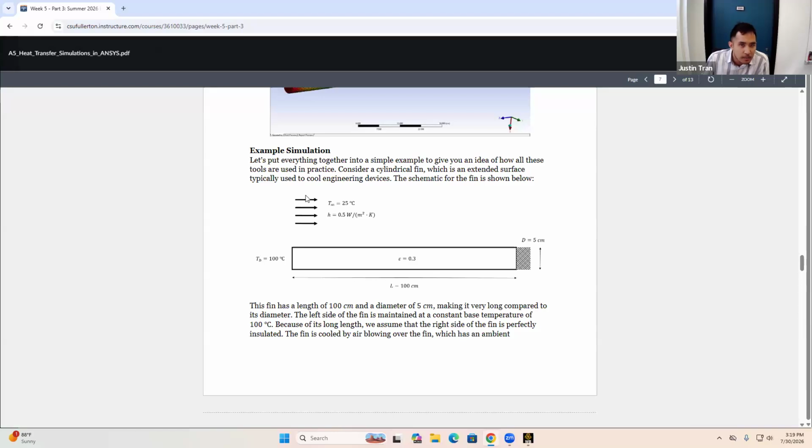And so you'd probably set it up the same way as we did yesterday with the modal simulation. You would just take one and drop it on the other so that they share solution information. I would probably do thermal first, just because with thermal it's usually a one-way street. The structural response is not going to affect the thermal response, but the thermal response is going to affect the structures. And so I would run thermal first and then drop the static structural on top of that, so it can share that coupling that way.